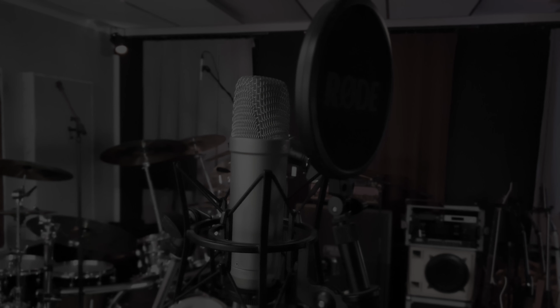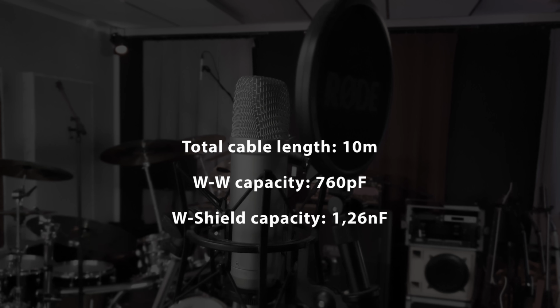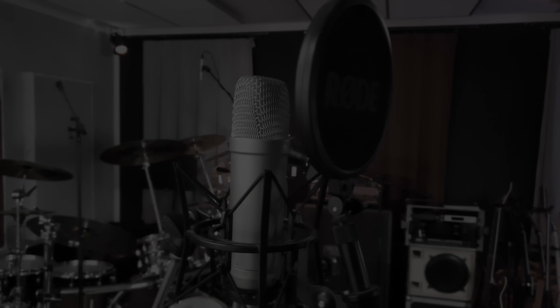Well, that's all nice, but what about some evidence, Tommy? Here you go! Ladies and gentlemen, now I am talking to a Rode NT1-A closely with a 10 meter cable and capacity of 760 picofarad wire to wire and 1.26 nanofarad wire to ground.